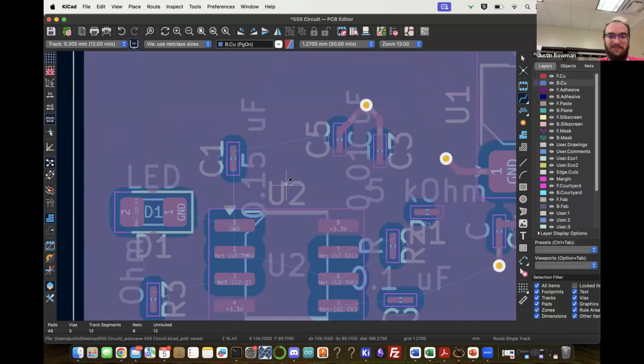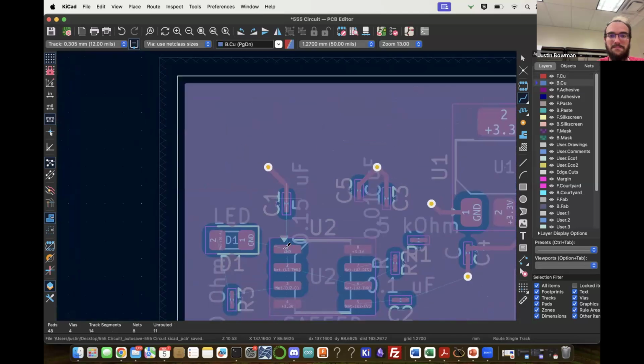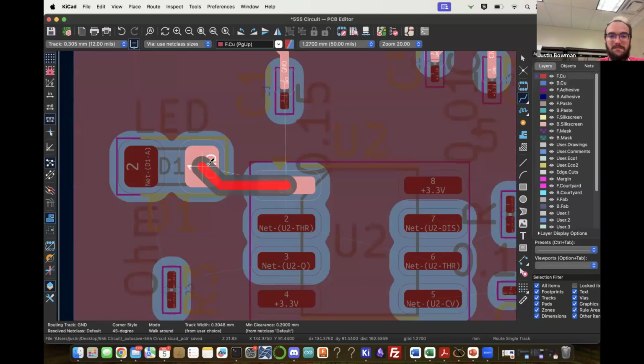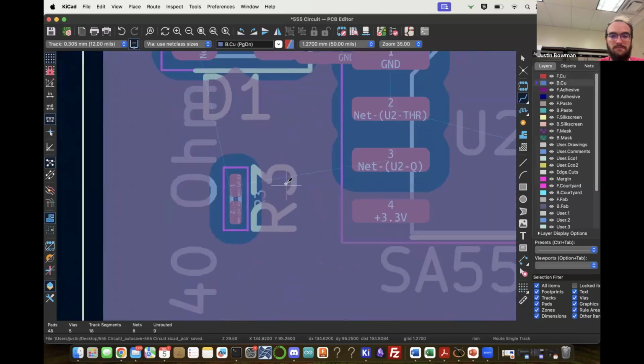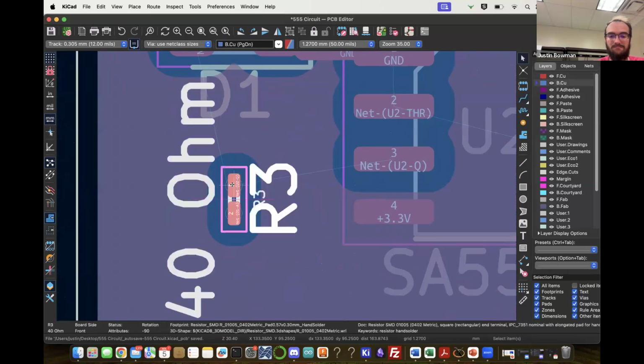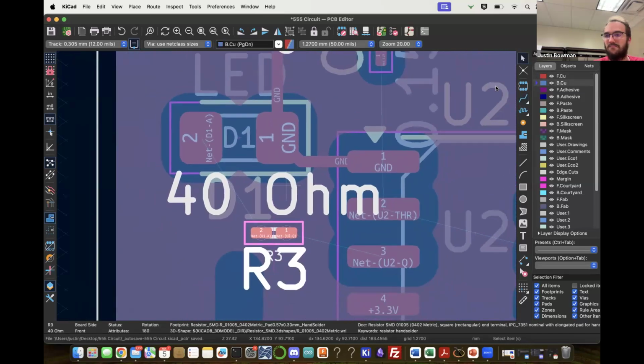That gives you copper on both sides and a small internal copper pipe. The vias are a standard size, correct. If we are actually manufacturing, you'll have to get the specification from them. They have a specific manufacturer, so just get that and make the hole that size and it'll work out.